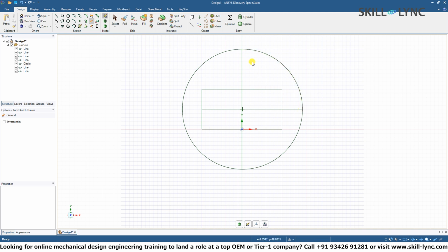What this allows us to do, as an example, let's say we want this rectangular prism sectioned off into 4 corners encapsulated by the circle. However, we have these 3 line segments over here that we do not wish to appear in our model. How would we get rid of them? This is where the Trim Entities tool comes into play.